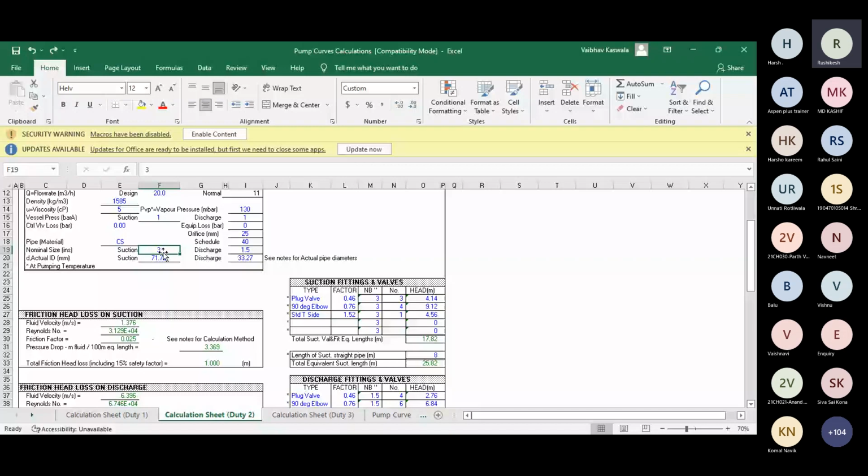So for our POCl3, suction side velocity is okay with respect to 3 inch line size. So our pressure drop, right, it is sufficient. Now again, for the suction side, what I will do, what are the different types of valves, different types of line and basically connections and fittings. So based on that, I will calculate what is the head, right?